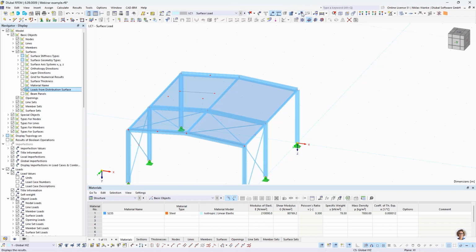And as soon as I start the calculation and the solver starts, you will see that there are two separate calculation processes. And that's a hint, because the first calculation process is made for the submodel, and after that we do the normal calculation process for our main model.